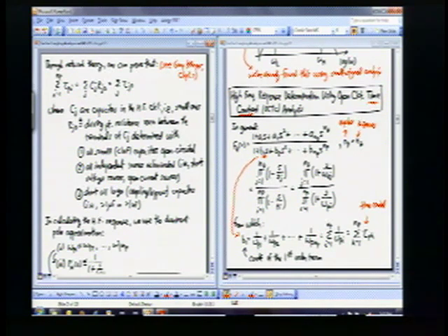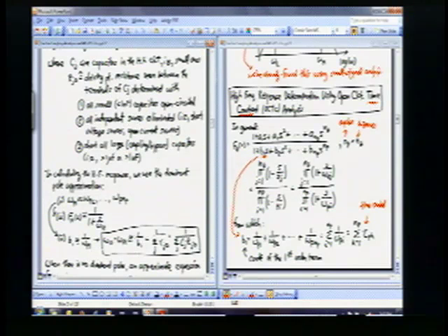And you're going to calculate a time constant like this for every capacitor in the circuit. So that's with the J. This is J from 1 to however many capacitors are in the circuit. You're going to add all those together, and what you're really getting is an approximation to the dominant pole. So that's where it's required that you have a dominant pole.